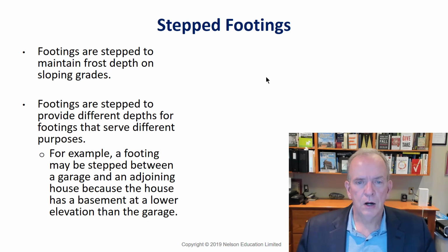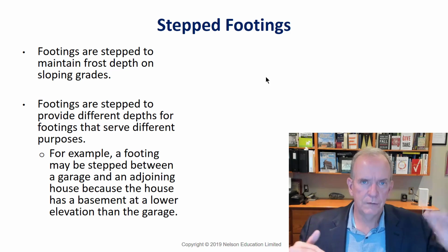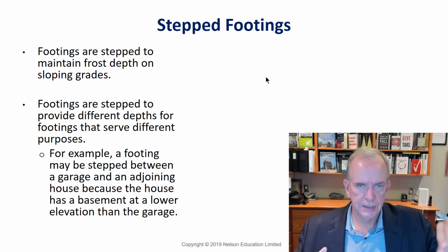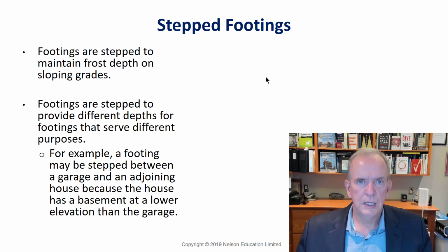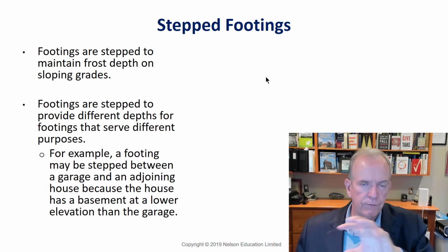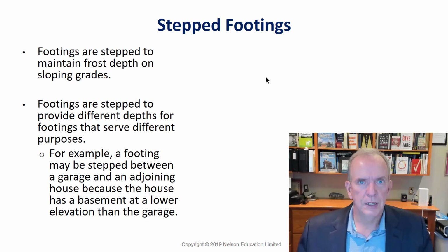Step footings are footings that are stepped, so that they have different heights, and that allows for differences in grade. It also allows for if you're doing a renovation and the footings are at different heights, so that you can step down to the existing footing of the house, or ensure that the foundation is stepped to it so that it's got full bearing wherever it's going.